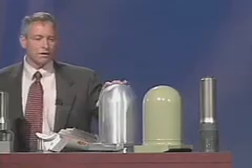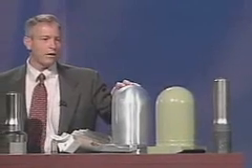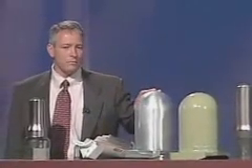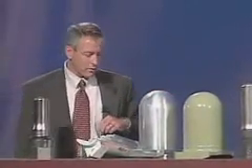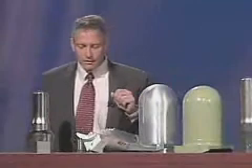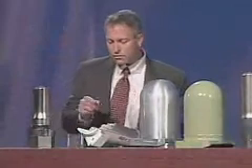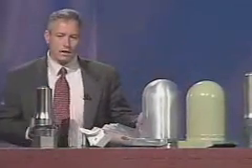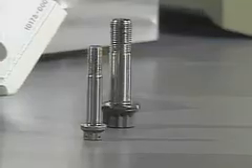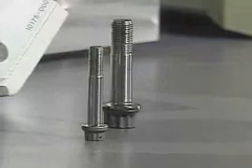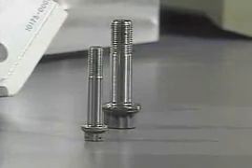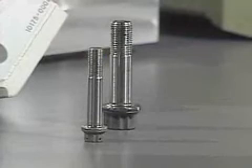So we've eliminated the weld by machining the bolt catcher out of one piece of aluminum, eliminating that failure mode. We've increased the thickness, increased the material strength, and eliminated the weld. We've also increased the size of the fasteners used to attach the bolt catcher to the external tank. We've gone from a 3/8 inch diameter bolt to a 9/16 inch diameter bolt.